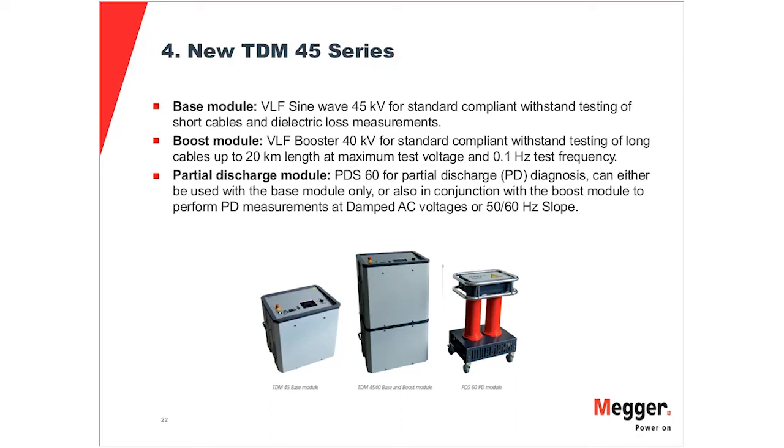And explaining you the item a bit more in detail, we have the base module, which is basically a sinusoidal waveform VLF equipment with the peak voltage of 45 kV, and it is meant for standard compliant withstand testing or pressure testing, as you may say, of short cable and dielectric loss measurement. So tan delta, with tan delta we are measuring the losses, and within the TDM45 series of family we would be using the sinusoidal VLF form to detect these dielectric losses within your circuit.